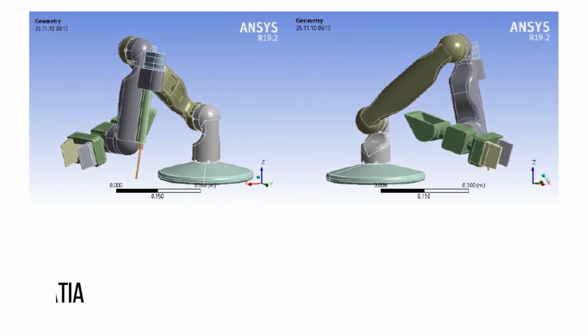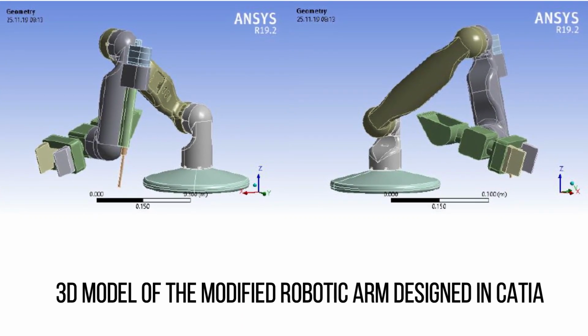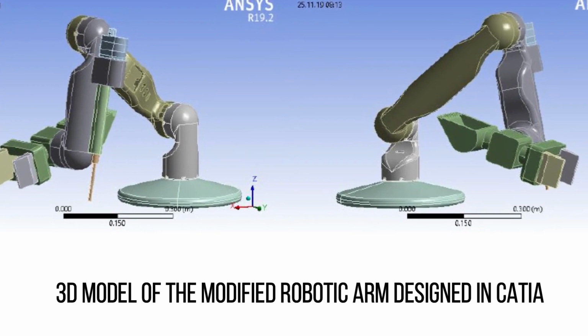Now the design involves the removal of unnecessary material without change in dimensions. The initial model of the arm is modified taking into consideration the dimensions of the motors and flexible flat cable connectors, and cutting as much weight as possible to ensure no stress concentration occurs. This is done because the torques obtained in the initial design are way beyond the torque rating of the motors.